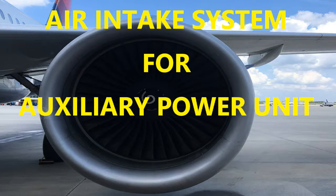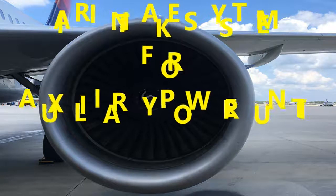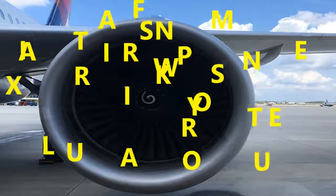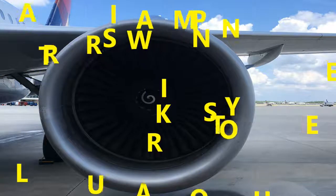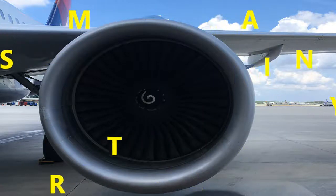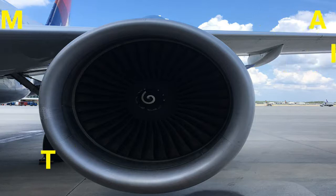All right, air intake system. What are we talking about? That's no different than main engines, right? All it is, is taking the ambient air and bringing it into that whole system, compressing that air, and then diverting it. With the APU, the components are your diverter, your air duct, and your air inlet, which has your inlet intake flap. That's part of it.